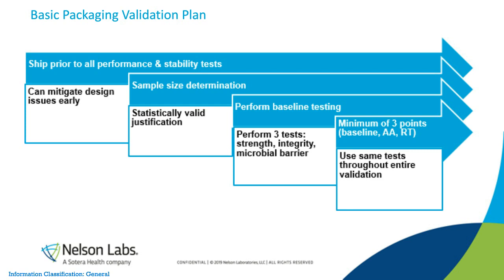The aging interval is usually the expected shelf life or the use-by date with some intermediate values. For example, if I have a 5-year expected shelf life, I would run testing at baseline and then again at 5 years. But I would also want to include at least one intermediate time point, say a 3-year or a 1-year or maybe both. That way, if there's a failure at 5 years, I can default back to the longest time point that passed, and that becomes a nice little insurance policy.